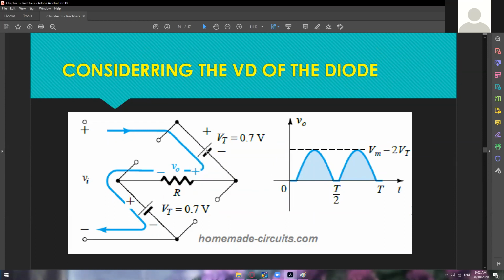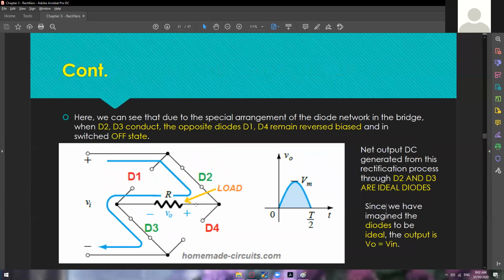But if this one is germanium and the other one is silicon, then you have to get the voltage threshold separately. So negative 0.7 and then negative 0.3. But since they are the same, then you can just say negative 2 times the voltage threshold, which is 0.7. Everything is the same. So if it's positive, it will pass through D1 and then D3, and if it's negative, it will pass through D2 and, am I correct? Oh, no, if it's positive, it will pass through D2 and D3. If it's negative, it will pass through D1 and D4.